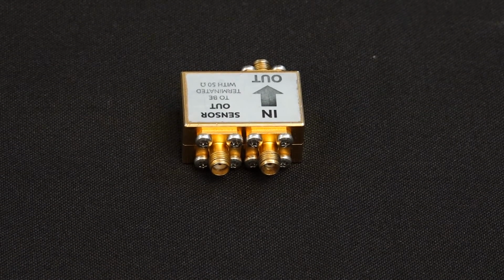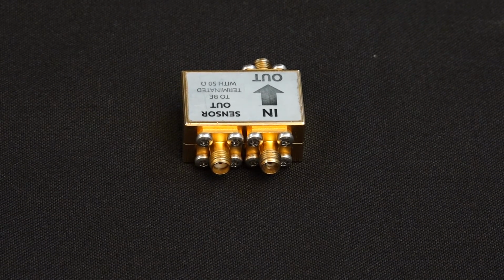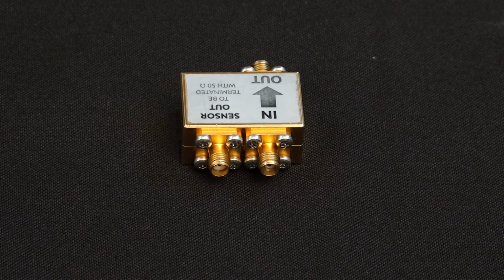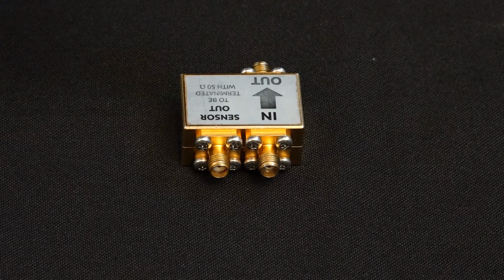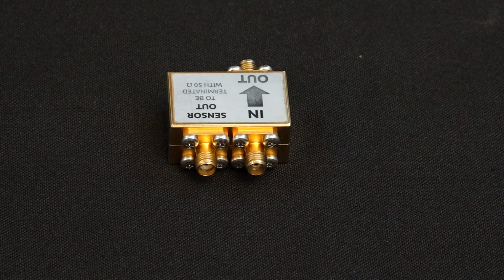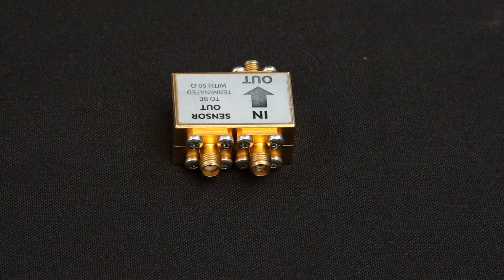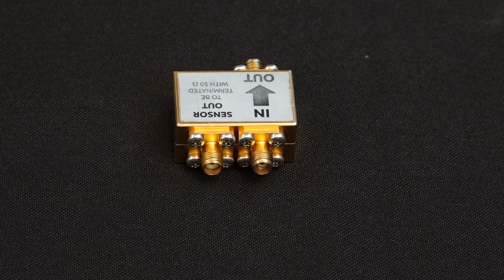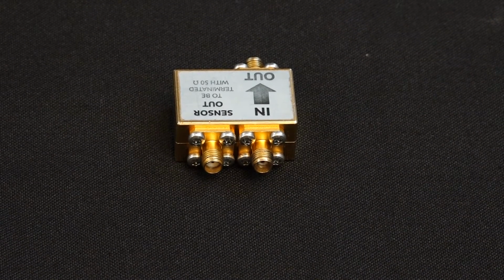Then the second thing is the sensitivity of a current sensor. Say for example, if I was to apply 1 ampere of current, the oscilloscope in itself cannot measure current, right? It can only measure voltages. So the oscilloscope will receive the output from this current sensor in the form of a voltage pulse, and that will depend on the sensitivity of the current sensor. For example, this current sensor has a sensitivity of 0.5 volts per ampere. So basically for every ampere of current, it will transmit 0.5 volts to the oscilloscope.